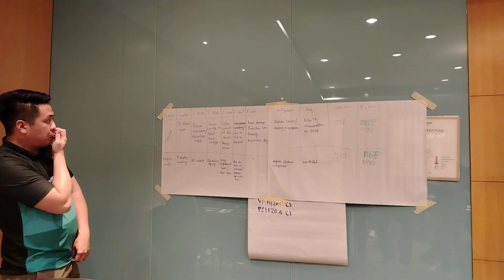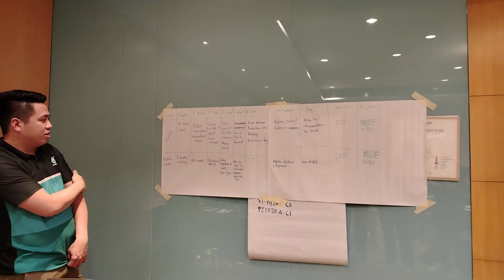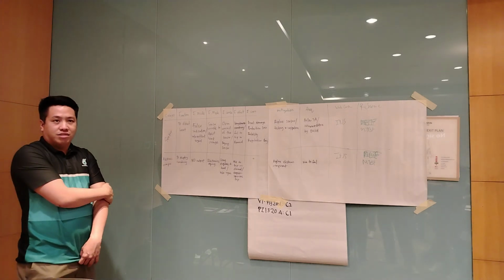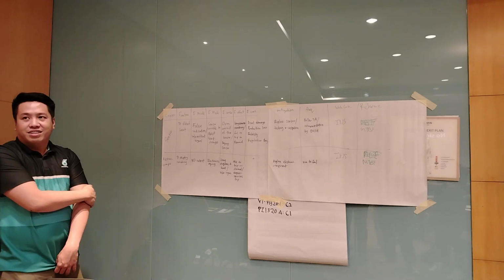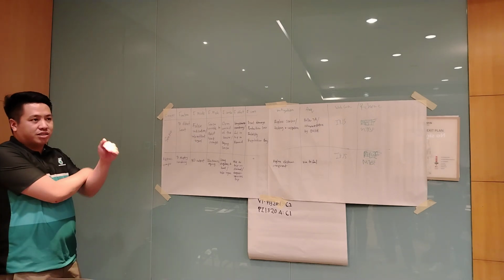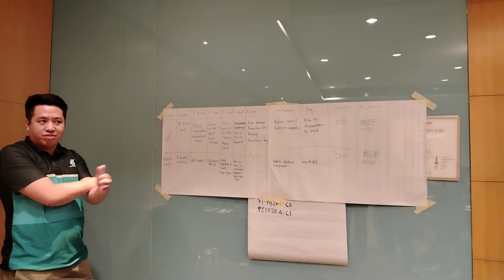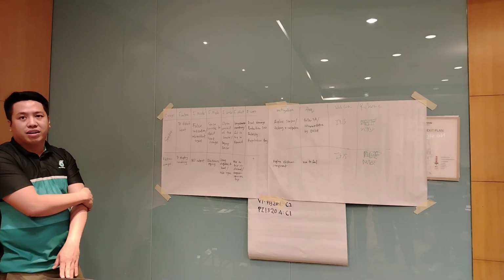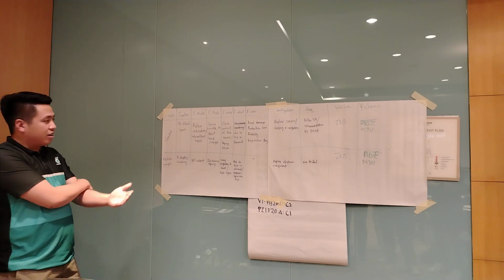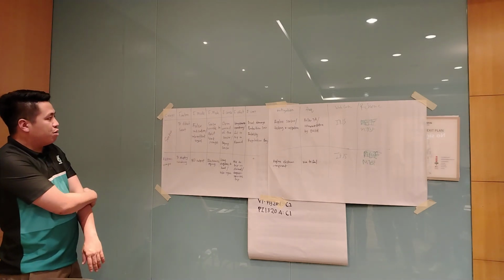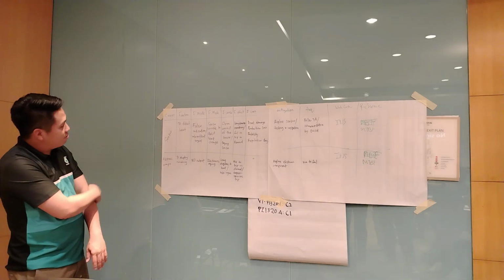The failure cause will be open circuit of the sensor or aging sensor. Anything can be aging, especially a sensor. All the time the sensor is directly exposed to the heat or the process medium, so it will tend to become aging. So the failure cause will be open circuit of the sensor.